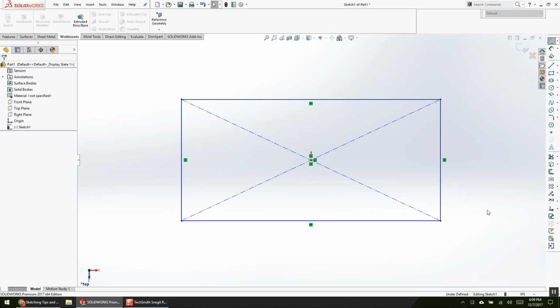So for example, there's screw holes on the bottom of this table, and with an origin in the center, I can now use the origin for symmetry, right? Because I've got the plane. So the first thing I would like everybody to realize, or what I try to lecture on in school, is planes are incredibly valuable. So where you put the planes in your model will drive value or remove your value. And planes are the most reliable.